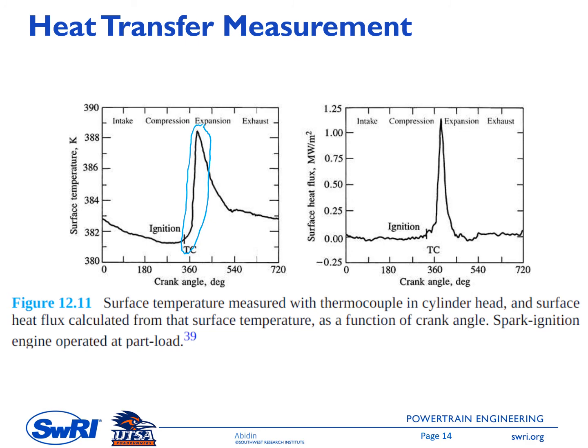So this tells us that the penetration depth of this transient gaseous temperature is much smaller. And then the figure on the right side is the surface heat flux, and the unit is megawatt per square meter. So it has the highest heat flux during the combustion process, and this is mainly due to the high temperature difference between the surface and the gaseous temperature.